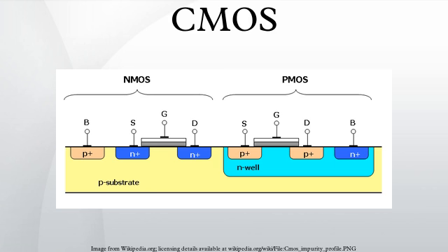Power, switching and leakage. CMOS logic dissipates less power than NMOS logic circuits because CMOS dissipates power only when switching. On a typical ASIC in a modern 90-nanometer process, switching the output might take 120 picoseconds, and happens once every 10 nanoseconds. NMOS logic dissipates power whenever the transistor is on, because there is a current path from VDD to VSS through the load resistor and the N-type network. Static CMOS gates are very power efficient because they dissipate nearly zero power when idle.